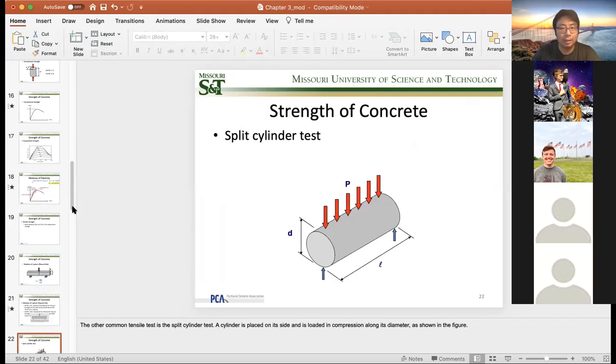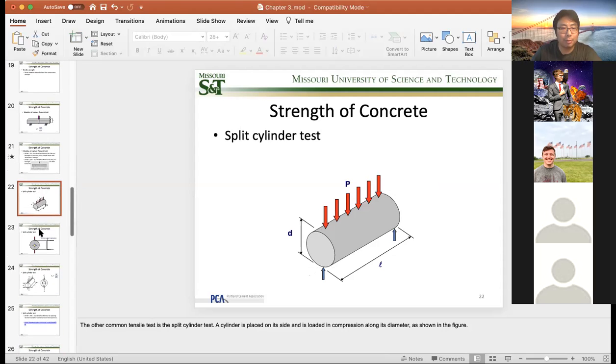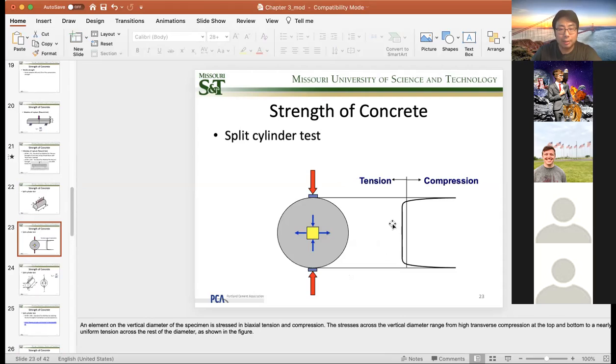Now for the tensile strength, there's another, faster way to get it, using the same cylinder. We apply a line of pressure on top of the cylinder, supporting it at 2 ends. Through this experiment we also get the strength, but the stress distribution is not uniform.